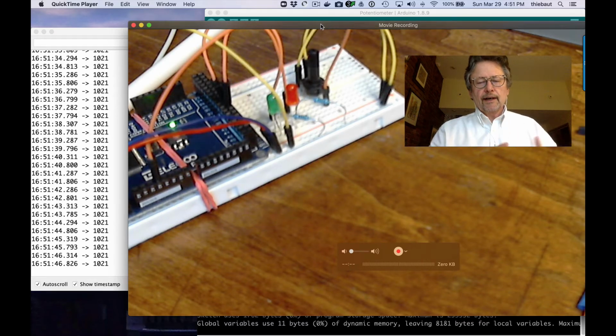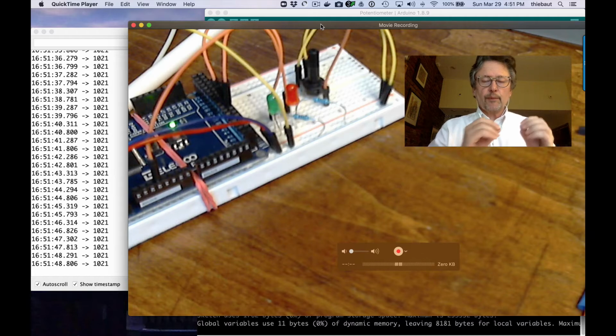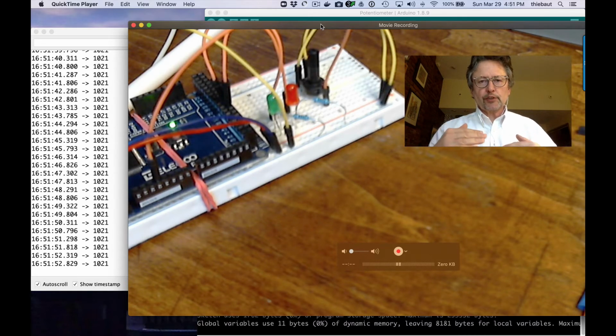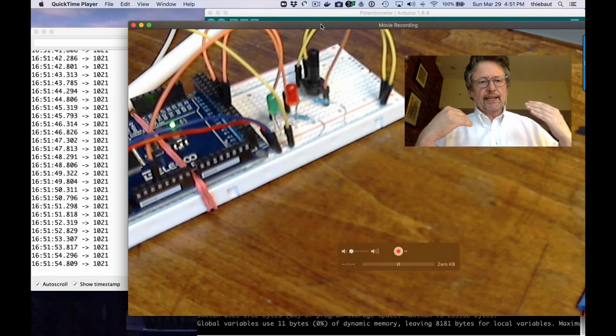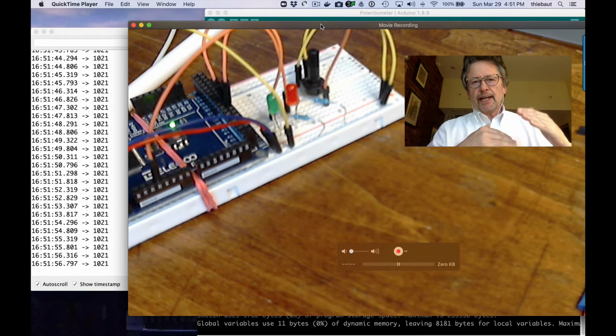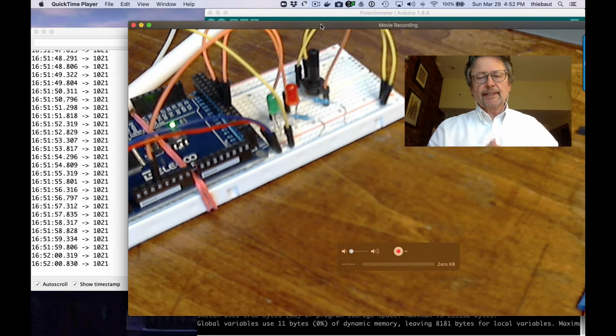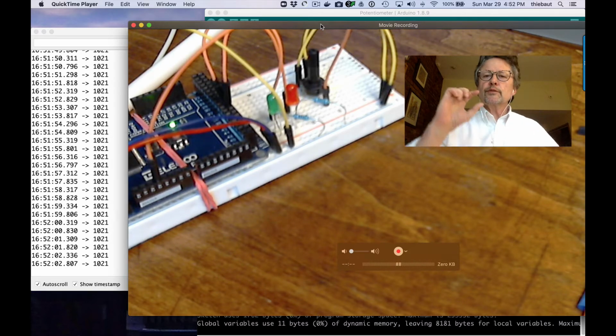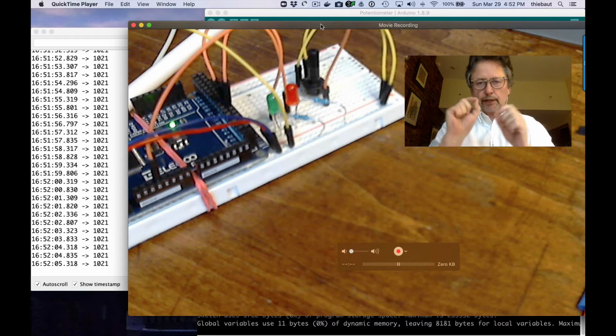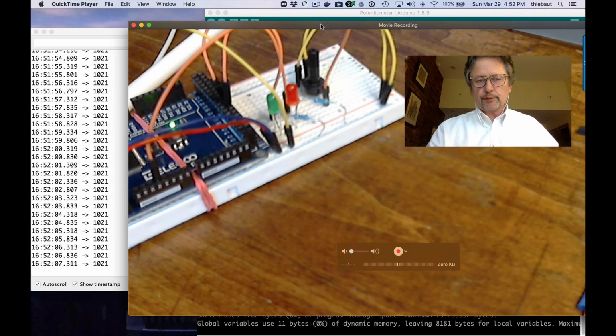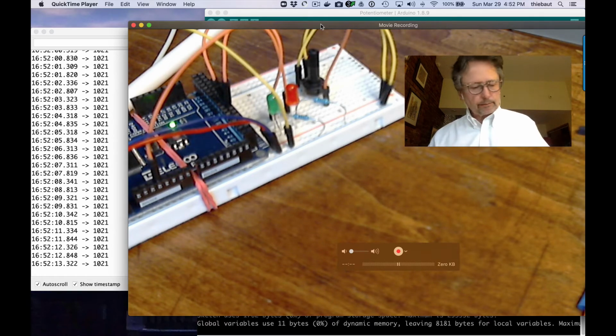So whenever we're testing for particular values, we're going to test within a range. If what we're reading from the potentiometer is between, say, 990 and 1023, then we'll know that it's high. So we'll just use ranges of values, rather than trying to get the absolute exact value. So that's the way it's going to work out. All right, so that's for that.